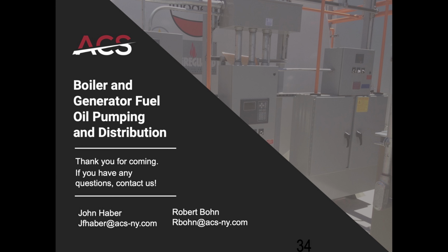Right, and I would recommend a header on jobs where the generator is in the basement and your tank is in the basement. That way you can install this system and not have a day tank where you'll have venting issues or overflow issues. You can have your header at the elevation of the injectors on the generator and be able to circulate from the tank back to the tank with minimal problems.